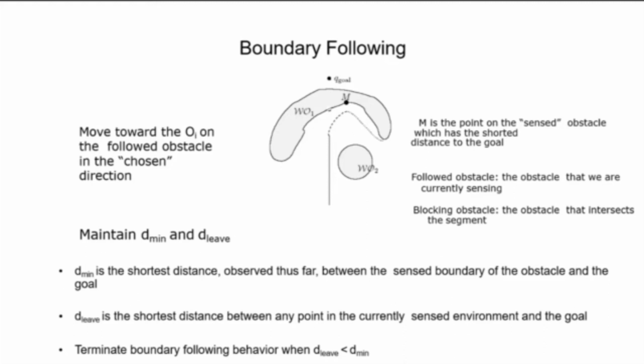So this is an example also where the robot was moving towards the obstacle. It finds the point M, goes towards M, but then after M, again this is concave. Okay, and this happens very often for concave obstacles. Now there is no other way, so it has to use the bug algorithm, or the tangent bug, follow the profile and then go like this and then come to the goal.